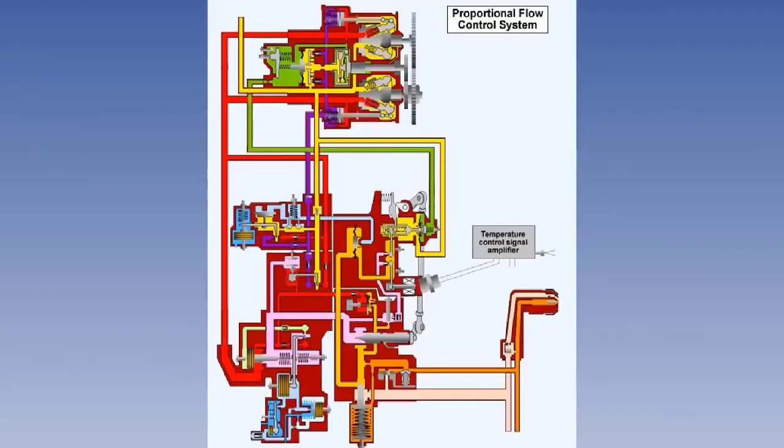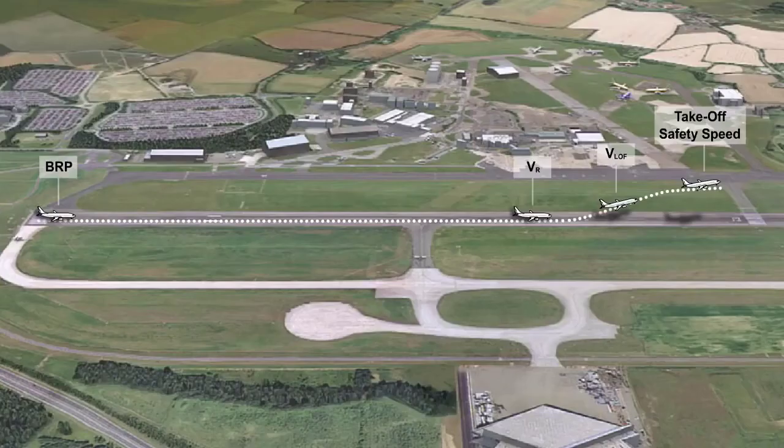In order to achieve correct combustion, the fuel-air ratio has to be correctly controlled. The fuel is mixed with the oxygen in the air in a ratio which is defined by weight. If the air is dense, more fuel will be provided and more power will be available. However, if the air is less dense, less fuel will be provided in order to maintain the correct mix. Therefore, less power will be produced.